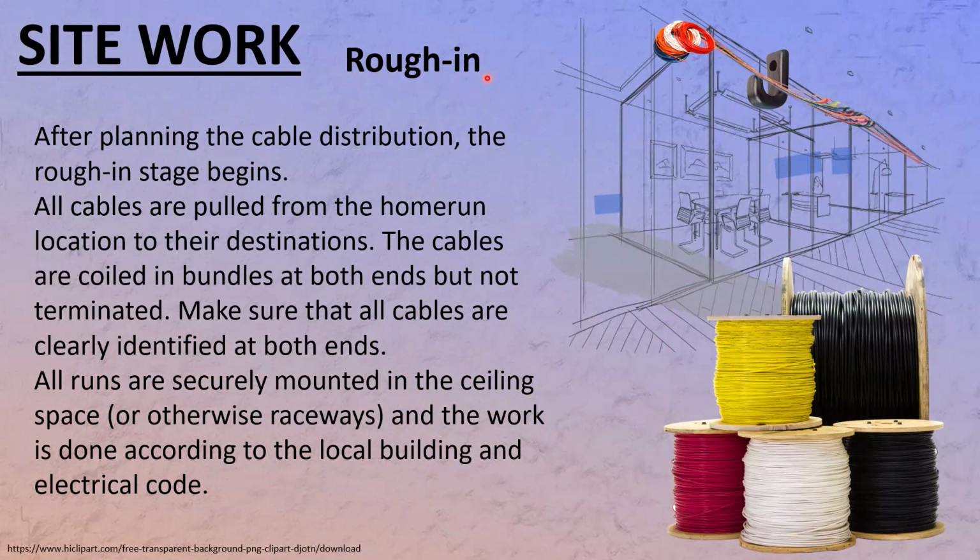When it comes to installing any kind of equipment that we install, wiring is a huge part of it. Big, big, big part of it. And then there's that so-called rough-in stage. We might have talked about it a little bit before. Rough-in stage is getting the wires to location. So if somewhere there's that main equipment room or LAN room, you're going to have wires to be pulled into this area here.